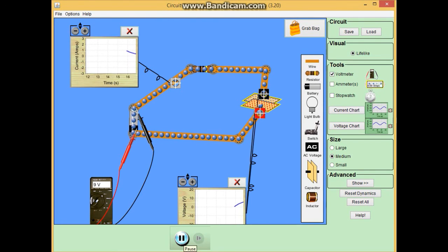And as you see here, this is the graph of the voltage across the capacitor as well as the current flowing through the resistor. The voltage chart has a positive slope, but the slope is decreasing, while the current has a negative slope, and it is decreasing in magnitude.